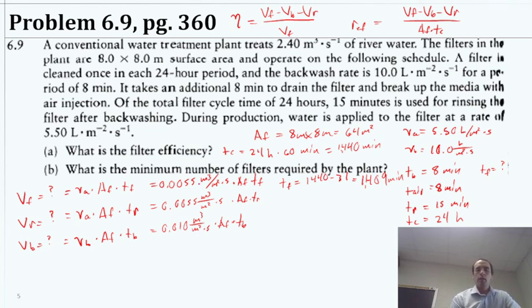And one thing I'm noting here is I think I may have, earlier in the slides, given typical flow rates that were much too high. I think I should have put them in liters per square meter per second, but I said meters, because these numbers are a lot lower than what I was saying earlier. So I'll correct those in the slides. Apologize for that. If you were actually to think about it, 5 to 25 meters per second through a filtration bed, that's really, really quick, right? And if you were to do the math on that, that would just be kind of bonkers in terms of how fast water is moving through and how much water you produce. So I apologize about that, but I'll go back and correct that.